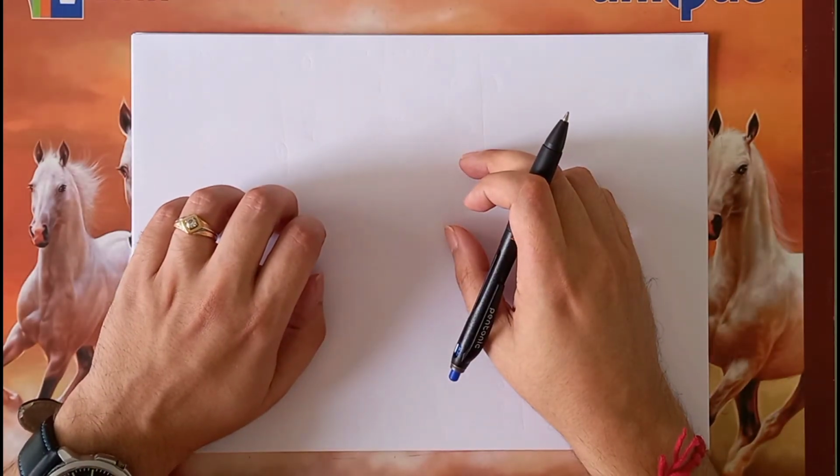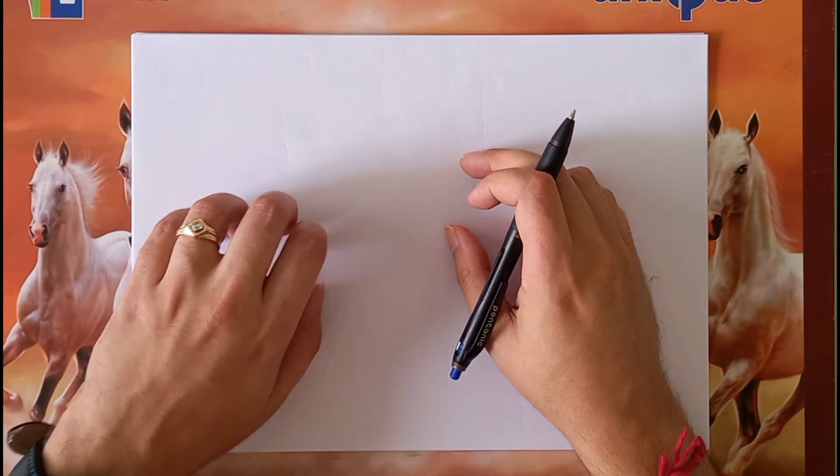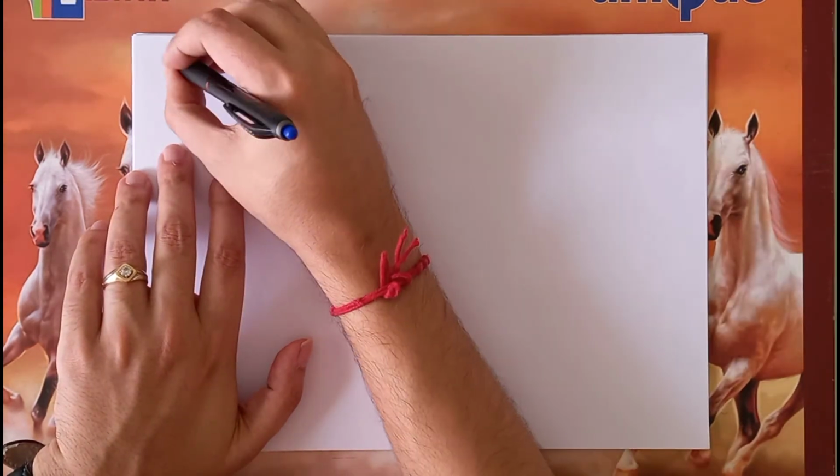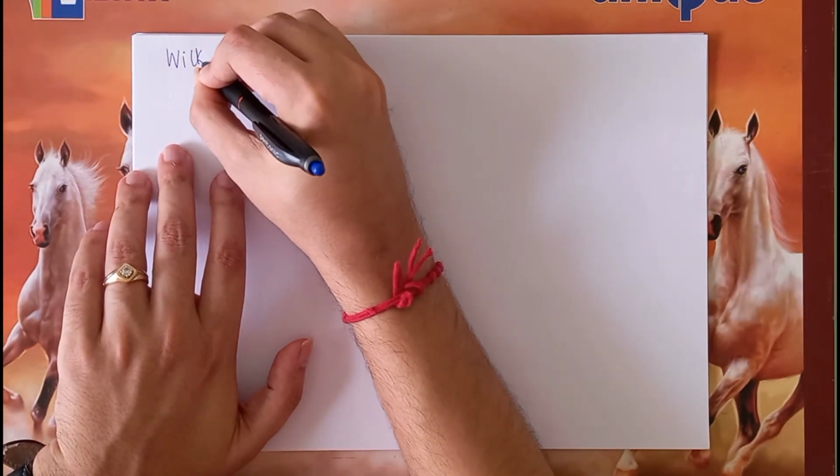So, towards the end of that lecture, we also discussed that Wilkinson, an American scientist, made an important but simple modification to the lossless power divider, and what he essentially did was to add a resistor between ports 2 and 3. So what it essentially looks like is this.